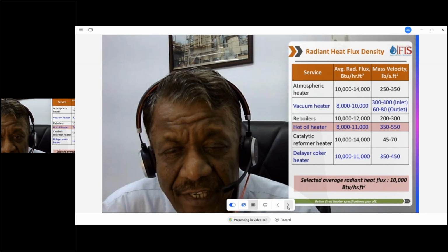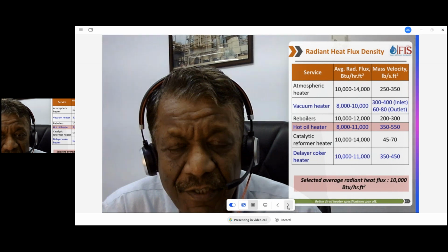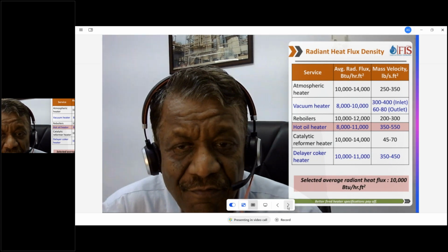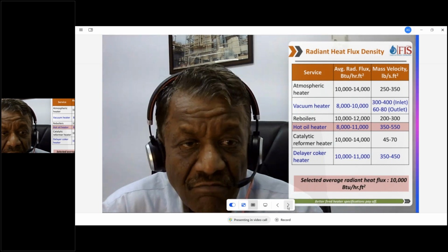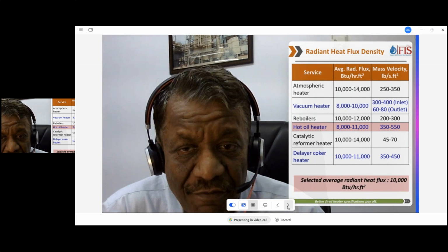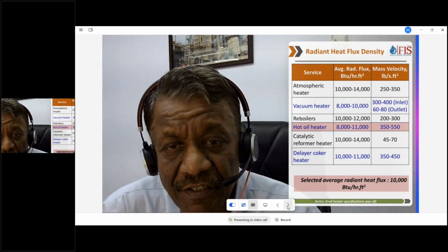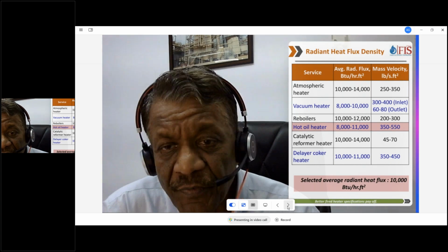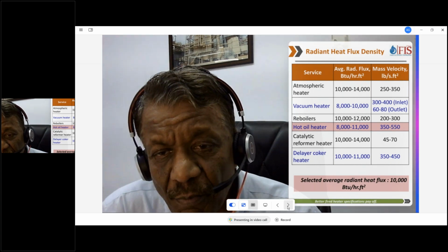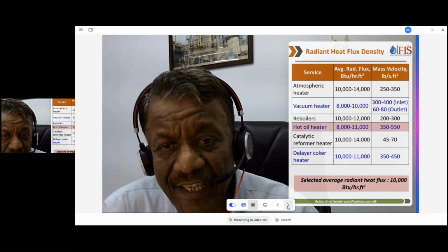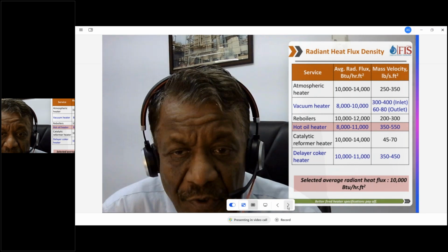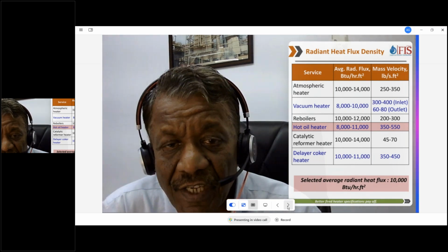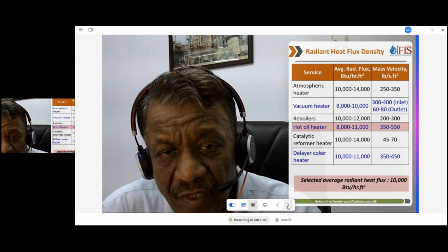And there, sometimes we use fluxes as high as 45,000 BTU per hour foot square. That's how fluxes go up in boilers. So a 100 million BTU boiler may be 1/3 the size of a 100 million BTU heater. So very, very different approach.